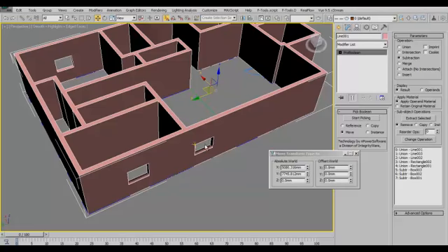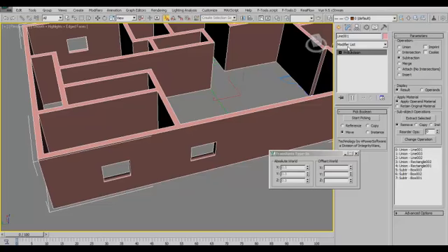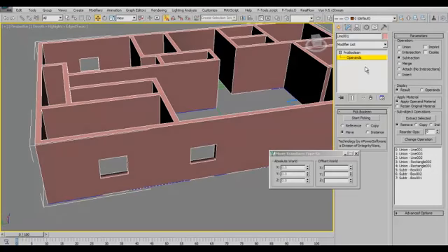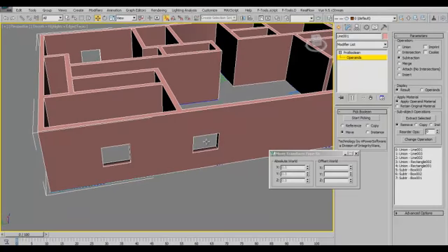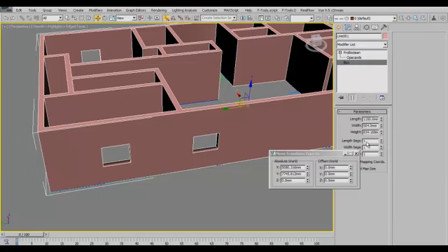So there are other methods actually. You can still modify this boolean, which from here you can, from your drop down from your boolean, pick operands, and if you highlight this operand, you can just start picking from here. You can see if you click twice, you get to pick the object. The object is there inside, though you don't see it, but once you start picking, if you take a look at what happens here, initially if you pick, it picks the original object, which is this wall originally, and you pick one more time, it picks the object itself. So from here you can now adjust your parameters.